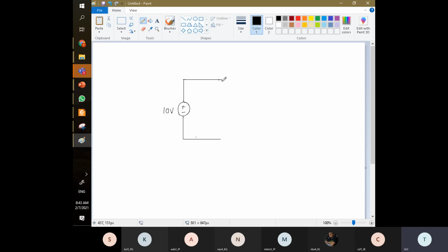Let's say you have only 2 resistors. One is a 9K. One is a 1K. So the two of them just add up to the 10 volts exactly. So you can say that the 9K, because of the more resistance, will take more of the voltage out of this voltage source. So when you measure it, you should get 9 volts here, and then you should get only 1 volt across these two points here.